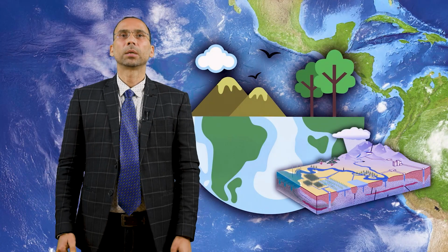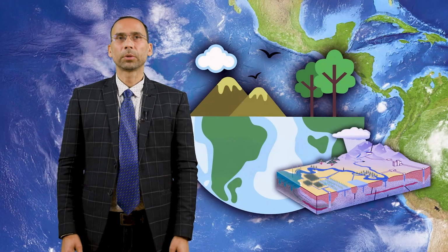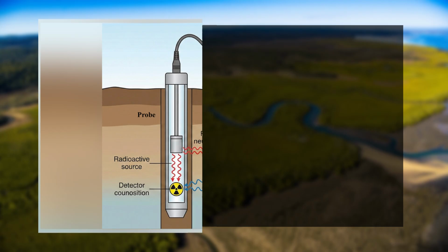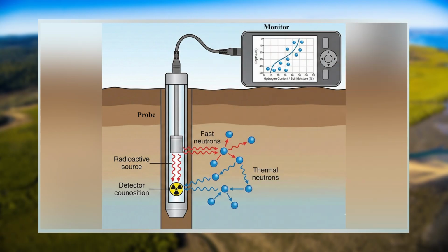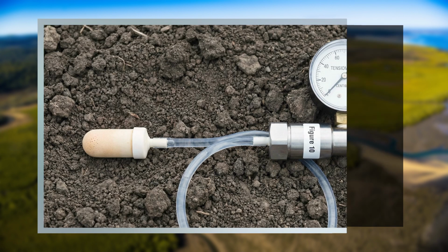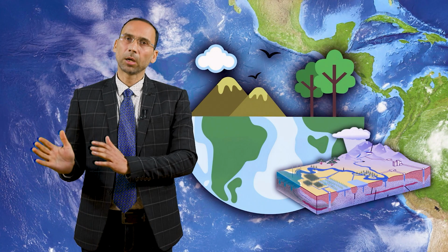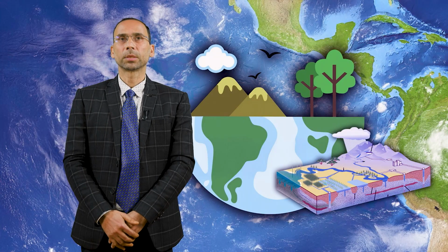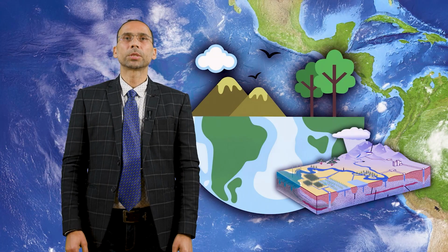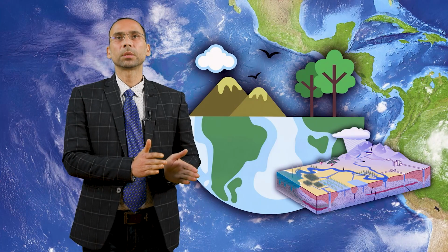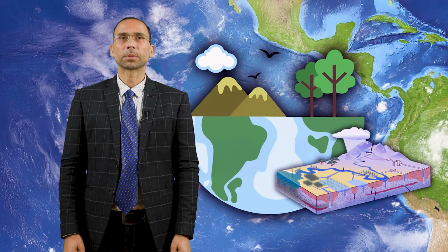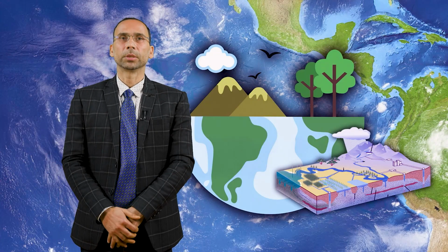The equipments are expensive and require frequent technical calibration. Neutron probes measure the depth-wise hydrogen content in the soil profiles. However, the probes need safety regulations. Similarly, capacitance sensors, tensiometers and heat pulse probes are also used. At large scales, microwave remote sensing is used. The volumetric soil moisture can vary from 25% to 45% in different soil types of India under different rainfall conditions.